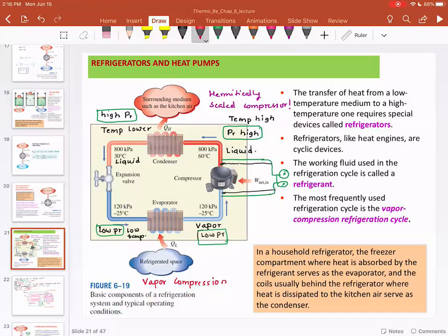That is how the air conditioning works in the aircraft. That's why, and this is an important observation, when the aircraft is on the ground, the air conditioning is not working very efficiently. That's why the flight attendants tell us to close the window so the aircraft interior doesn't get heated up. Because when the aircraft is stationary, you don't have compressed air.